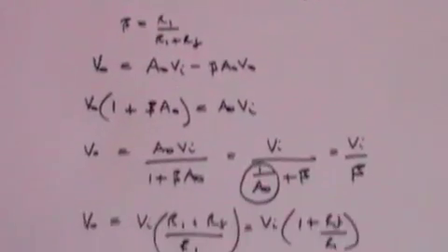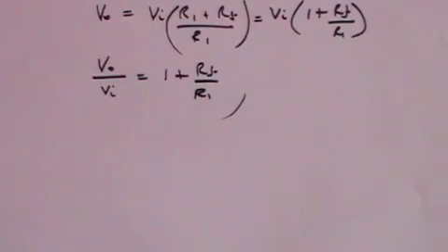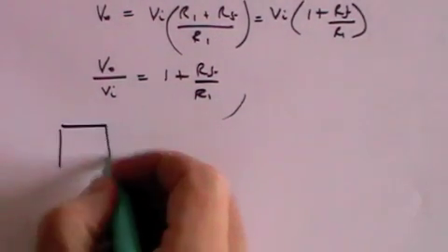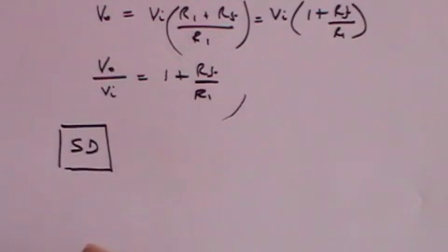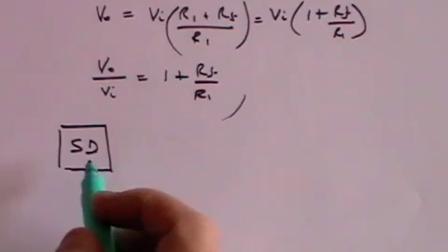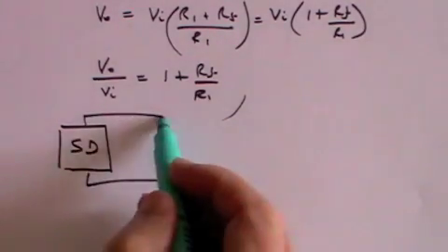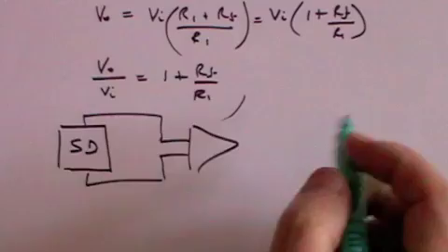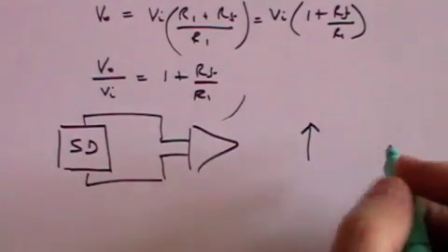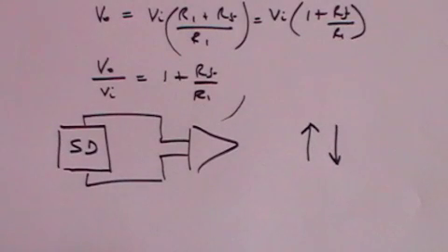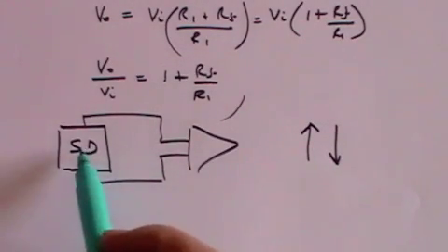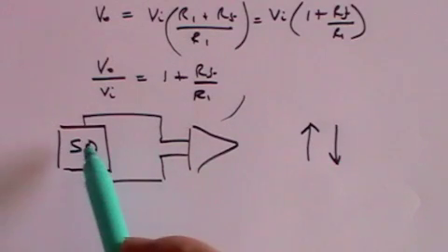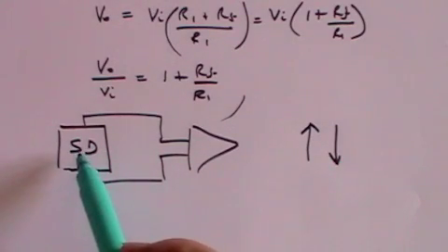Well, let's just remind ourselves where we've got to. We started off by identifying that we can have a sensing device which usually changes resistance as the thing that you're measuring varies. And then we said that you can put that sensing device into an electronic circuit which also contains an operational amplifier, and that will produce a voltage which is either positive or negative. And the trick is that you want the voltage to change direction when a certain key point is passed with the sensing device.